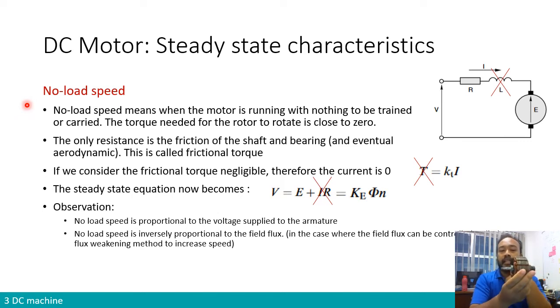But as I mentioned, it cannot be completely zero. Why? Because we can see that the shaft will be mounted on two bearings, one on each side, here and here. So it's mounted on bearings, and therefore the bearings have a small amount of friction, so there is a certain small resistive torque. Added to that, there is basically here your commutator.